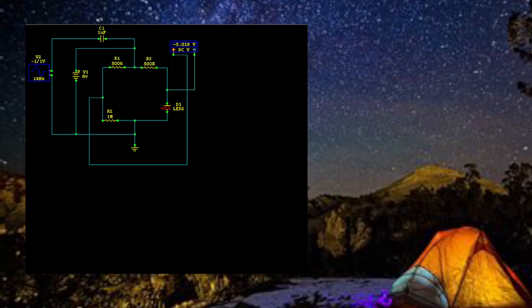It would be nice because there's other parts of that circuit that are going to be built. There's an FET preamp that's supposed to be built. Then that goes into a couple of op amps which drive, you get a better signal because it's amplified. It's a very small signal. Like, we may be talking about microamps here.